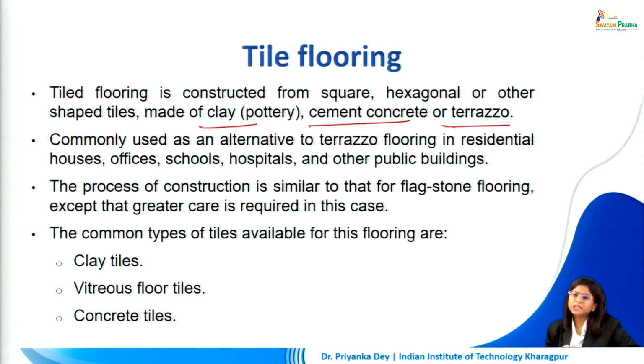One must select the type of tile carefully when dealing with public buildings. If the floor receives a lot of foot traffic, or heavier furniture is expected on the surfaces, it is better to go for tile flooring which is able to resist that wear and tear over the duration of the building's lifespan.